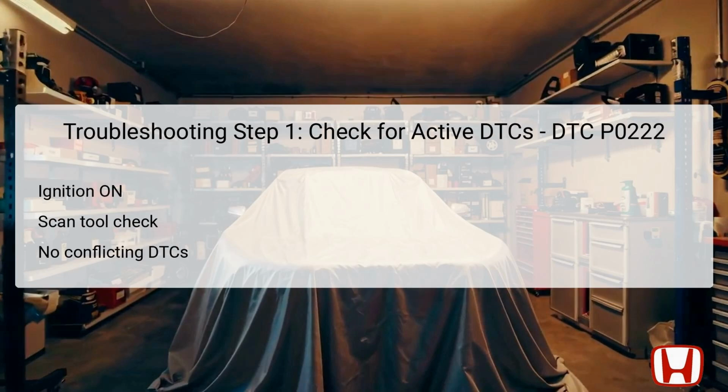The first troubleshooting step for diagnosing the DTC P0222 involves checking for any active diagnostic trouble codes using a scan tool. Begin with the ignition in the on position. This action allows the vehicle's onboard diagnostics to initialize. Next, use the scan tool to access the PCM and check for any active DTCs, including those that may be conflicting, such as P0122,